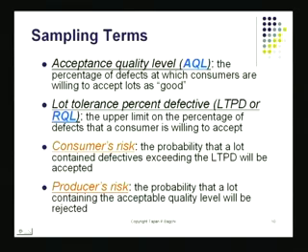Let's take a look at a couple of other things. Suppose my lot has been received at the RQL level, which is also called LTPD, lot tolerance percent defective. This is certainly the rejection quality level. Now, because I'm not doing 100% inspection, I'm inspecting just a handful of items. I'm just inspecting a small sample that has been drawn out of the full lot.